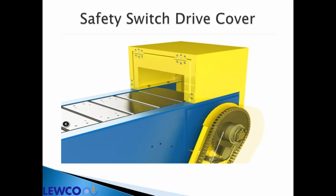This is a safety switch drive cover. What happens here is if a customer is running product down the slat conveyor and they're working on it and one happens to slip through, if it reaches this safety switch, it'll push up and the entire conveyor will shut off until the product's removed.